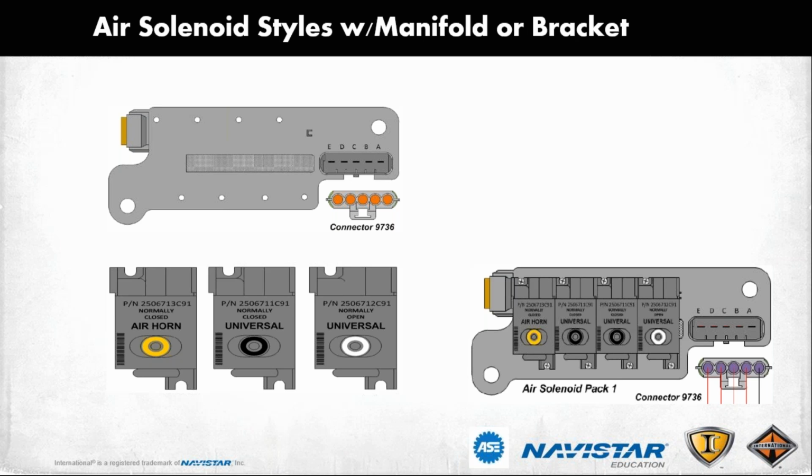This is depicting a pneumatic or air shift PTO. We have the options for an electric shift or air shift. This is an example of an air shift. You see the feedback signal going back into the body controller. With this, we can program in 42 different parameters. They have rules of engagement. So say the driver wants it to only engage below 3 miles an hour. They only want it to engage below 800 RPM. Those are rules of engagement.